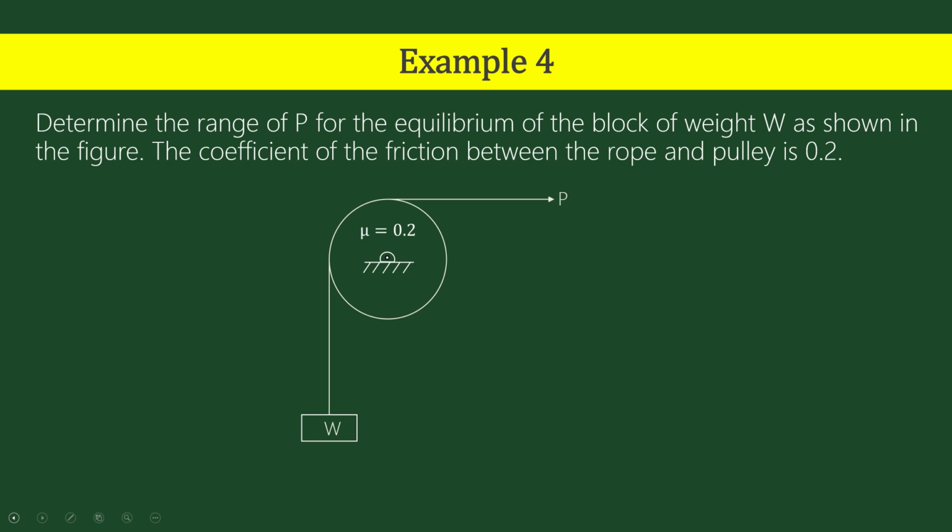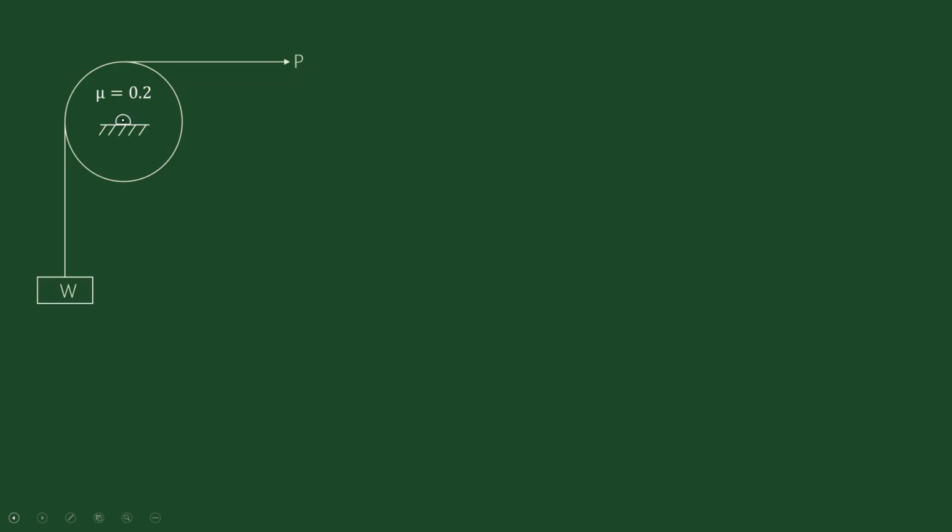So, first of all we are going to find out the value of beta now. What is the observation? W is from the extreme left end and P is attached to extreme top. So, if you draw a normal from that point of tangency, you can observe that pulley is in contact with the belt for 1/4 of the circle, and if it is for 1/4 of the circle, beta is 90 degrees, or we can say that beta is equal to pi by 2.